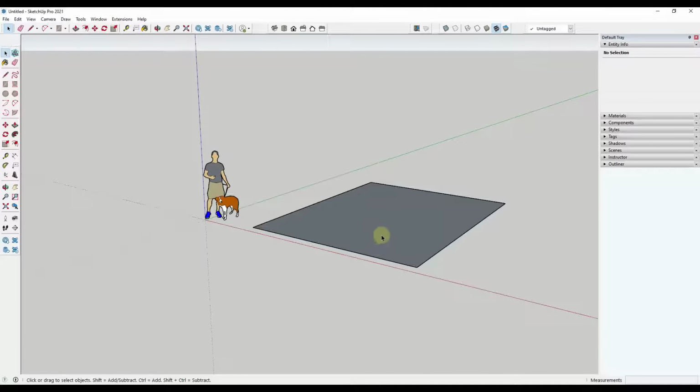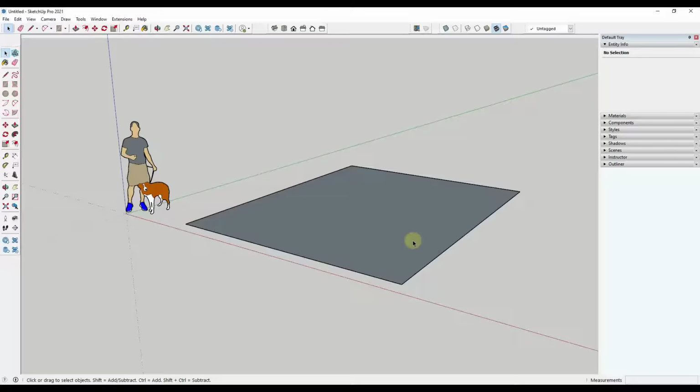And now what we want to do is we want to take this into 3D by extruding it. And so we're going to extrude it by activating a tool called the push-pull tool. You can find that over here, or you can type the P key on your keyboard. And so note that I'm using a lot of keyboard shortcuts because keyboard shortcuts are a lot faster than clicking on the icons over here. So for this one, for example, notice how I'm tapping the P key on my keyboard and then mousing over this in order to use the tool.